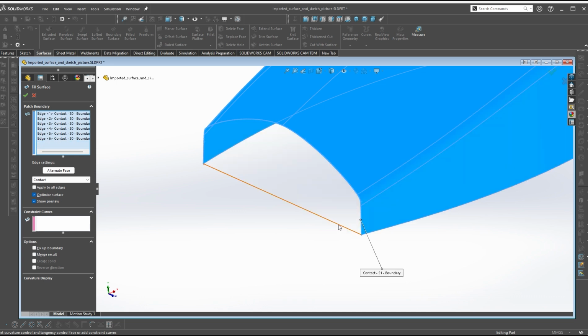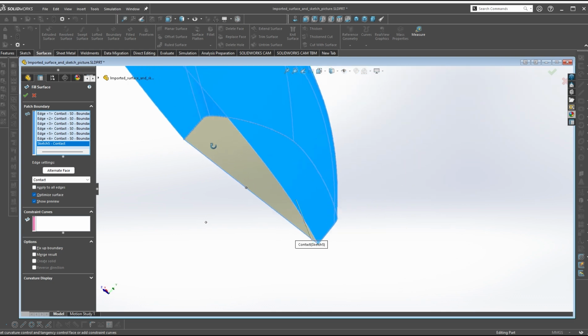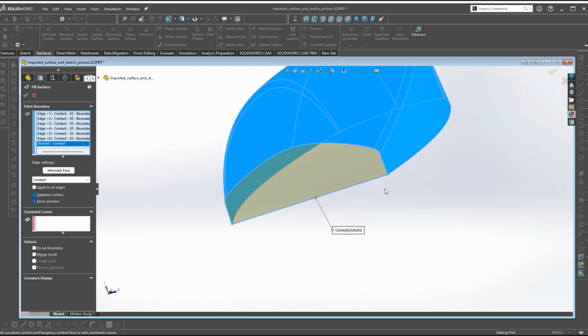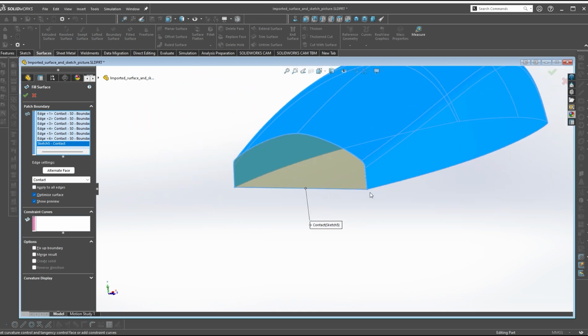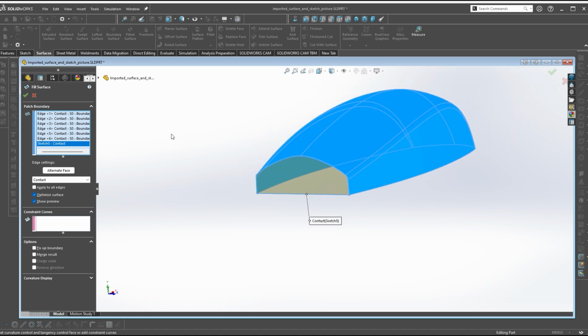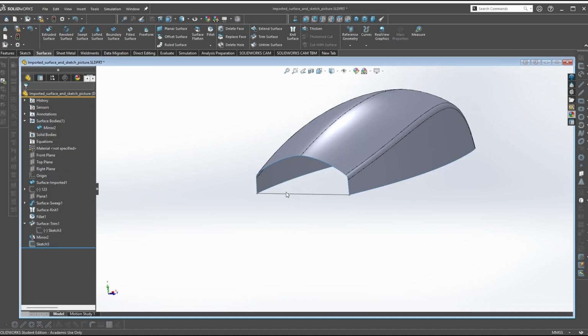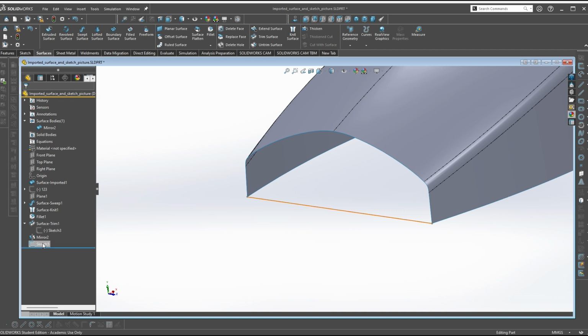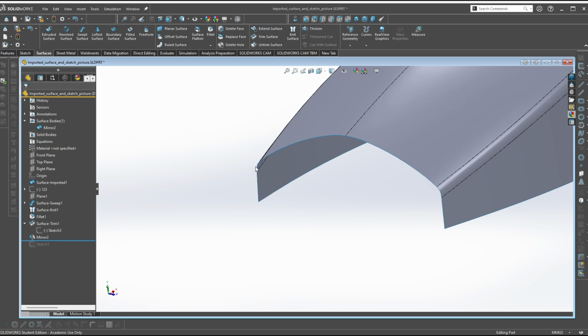Okay. This would probably work okay. In some cases, SolidWorks likes single entities to work with. So I want to show you that just in case this creates more accuracy or a more accurate result for you. So let's move up one here. So we're going to just go above that sketch I just dropped in. And let's use a 3D sketch.